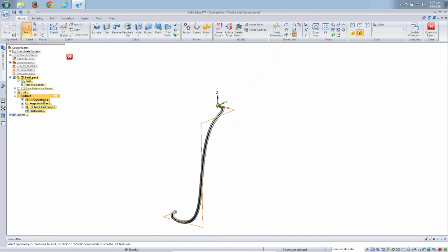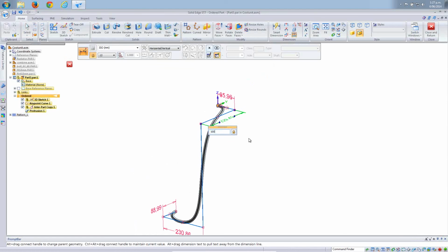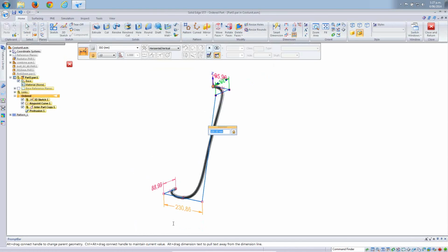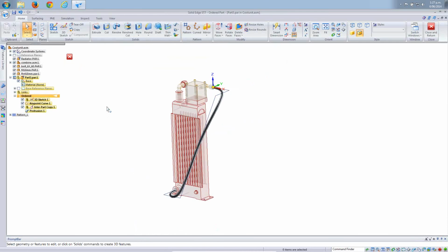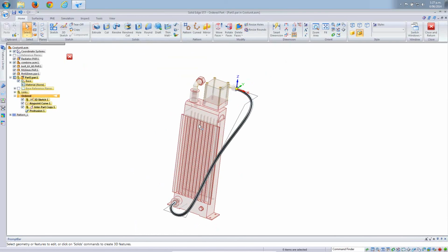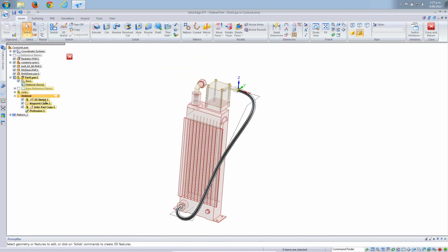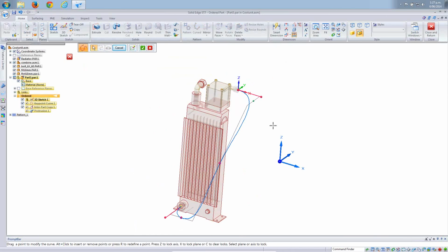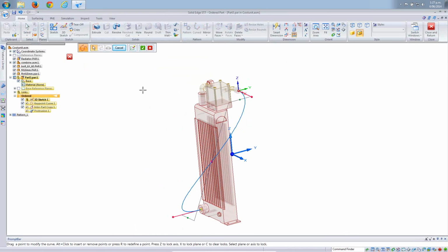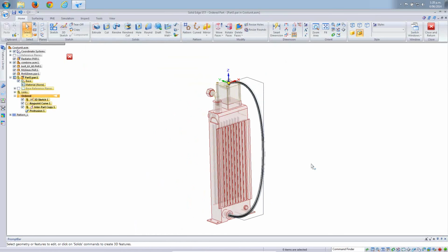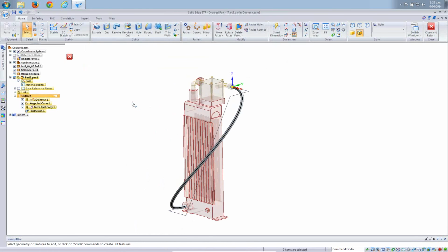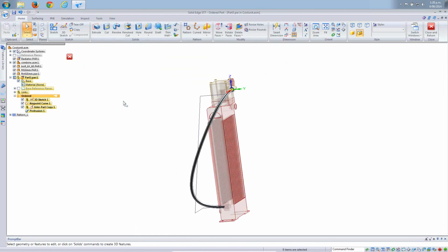And then if I make any changes to this sketch, you can see that the path, the key point curve, is updated. Let's turn the rest of the parts back on so I can make modifications to this path at any stage. If there's too much control, or I don't like the controls that I've got on the key point curve, then we can go ahead and remove the ones that we don't want, or I can add them back in again. So actually maybe we'll just look to remove. There's a little bit too much control. I've overcomplicated my path. And so the advantage of doing this in ordered is the way that that's just updated. So if this was synchronous, then the sweep would not be associative back to the key point curve, and that's kind of important, I think, in this little demonstration.